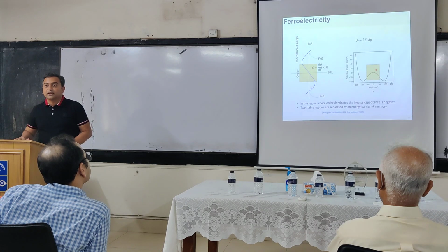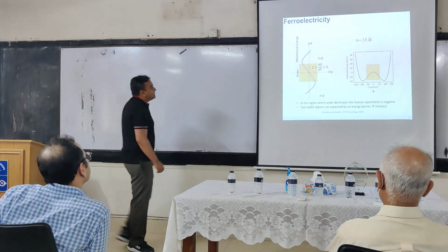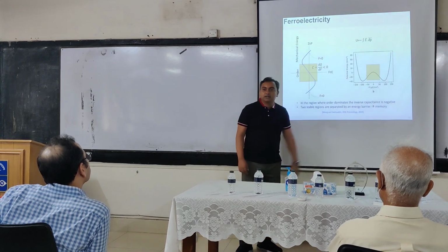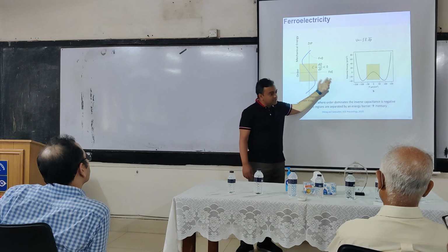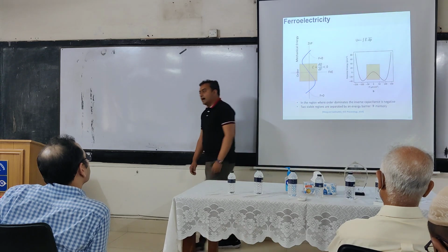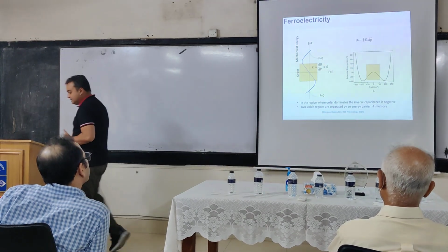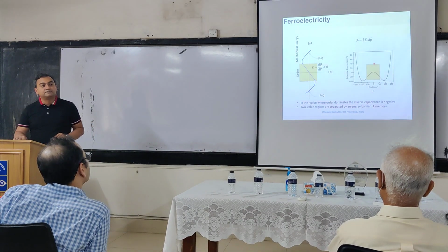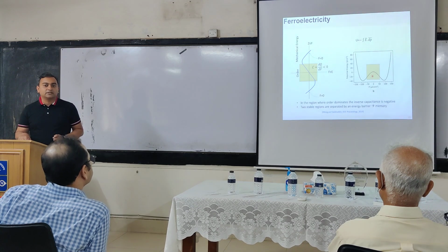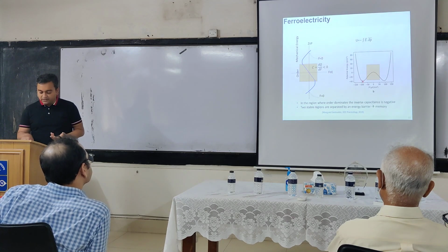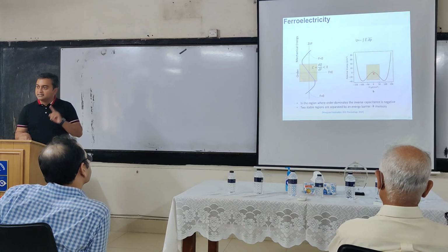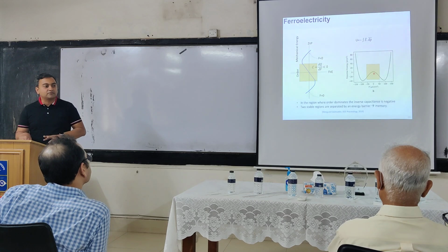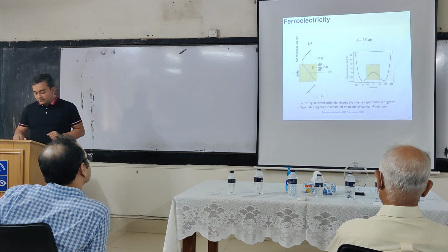Make sense? So far I have not said why I am even interested in this. We will talk about it. But negative capacitance by itself is interesting. So right here I see negative capacitance. I also see that this thing is not achievable. Why? Because this region is not the minimum energy position for the material. So if I just take a material, it will be here or there, and there it is not negative capacitance. It has a region where it has negative capacitance, but it is not there by itself. So I have to do something to achieve it. So that's what we will see.